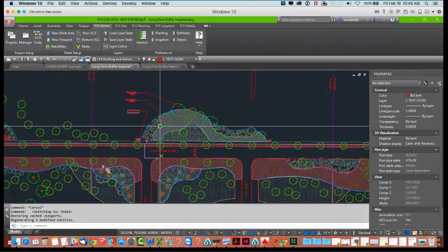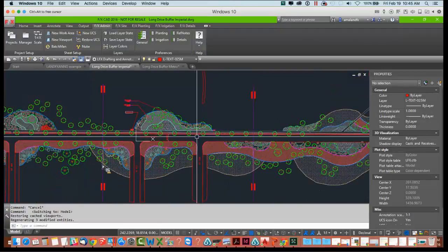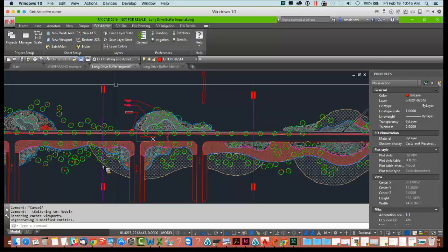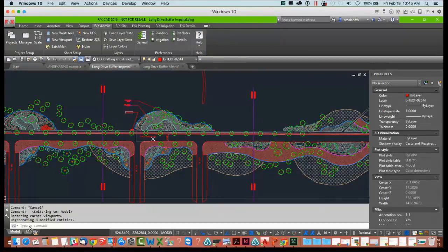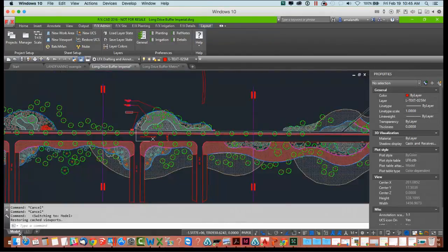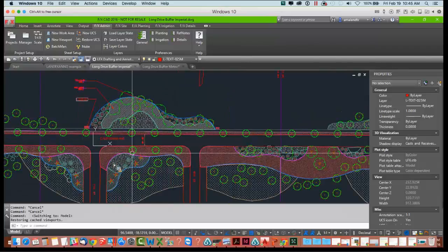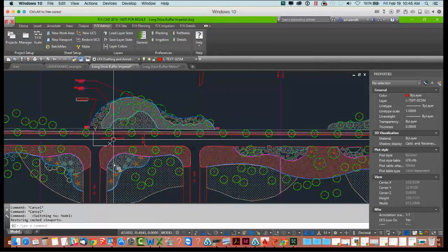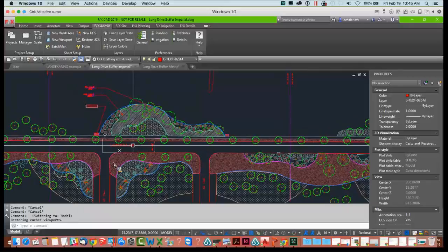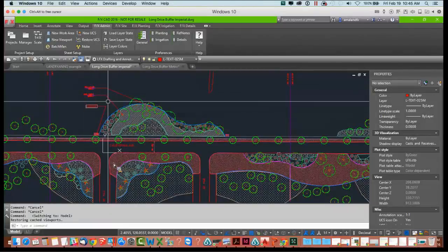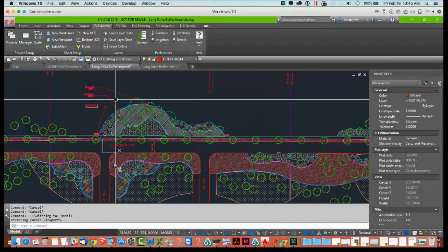So first off, in this scenario, my scale is 1 to 30. I need to change it to 1 to, what am I going to be able to fit on the page? We'll do 1 to 20. So I need to change this to 1 to 20. Well, I have a dimension, I have a California Avenue, I have a reference note, I have a callout, all of these things that need to rescale.